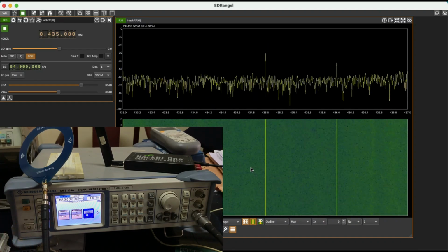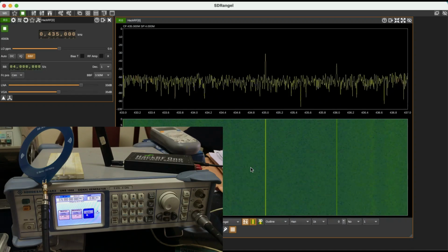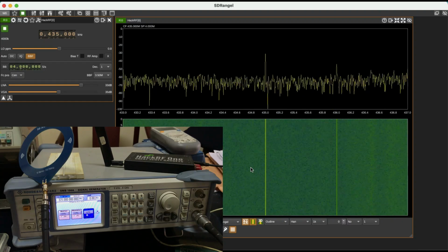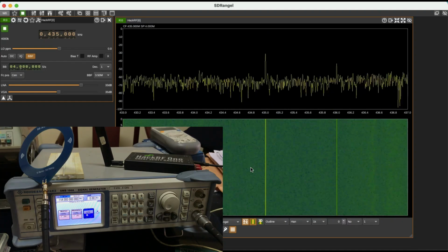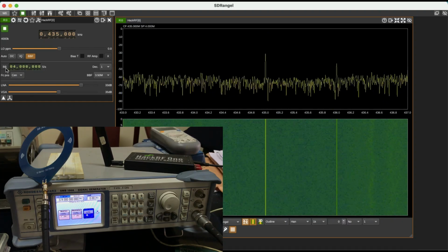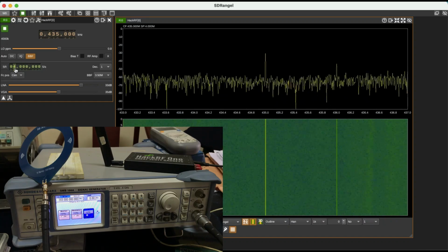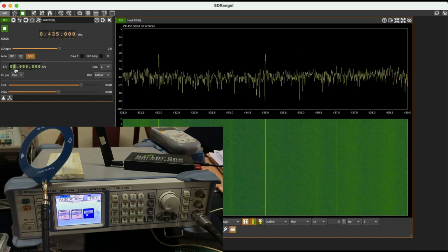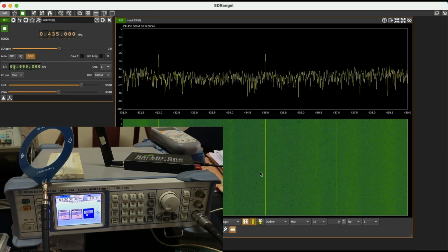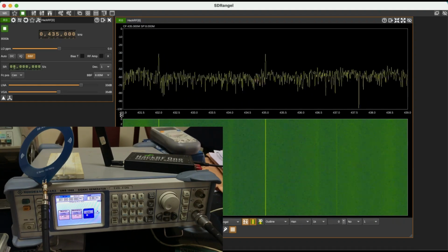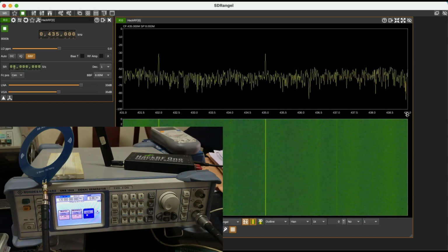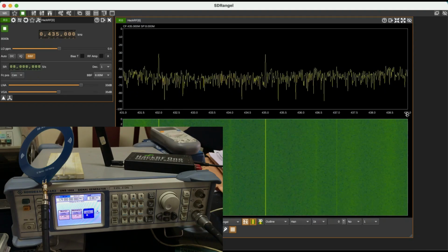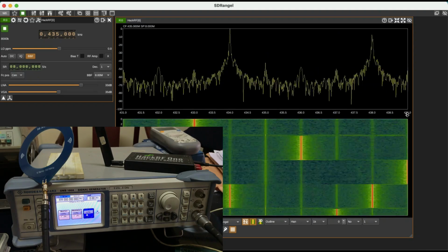Because I was unable to see the spectrum previously, because I can only visualize the spectrum from 433 megahertz all the way up to 437 megahertz, I can just increase the sample rate as well. I can go up to 8 mega samples, and I think even 10 with HackRF. So this is what you're seeing. You're seeing from 431 megahertz all the way up to 439 megahertz. So this is just sweeping around, transmitting that frequency and moving along, transmitting this frequency and moving along.